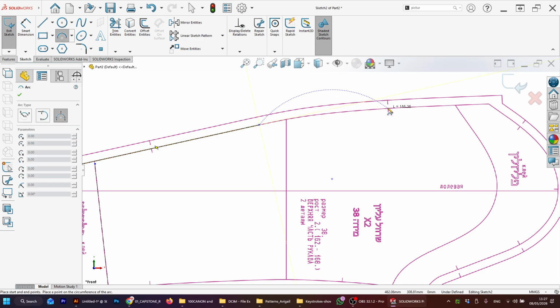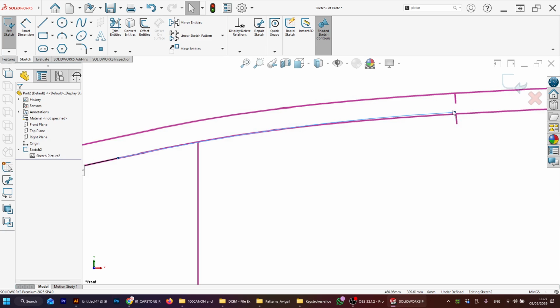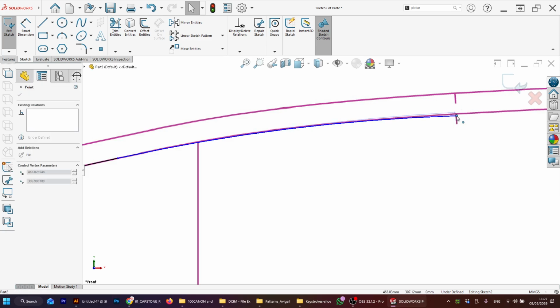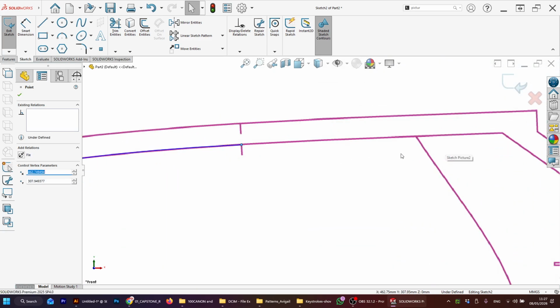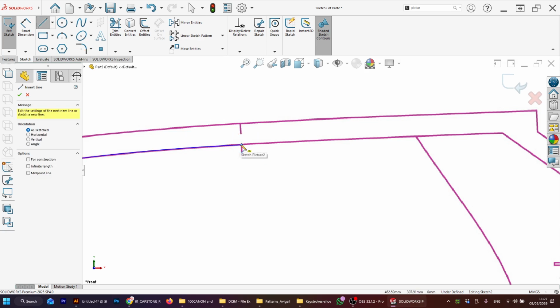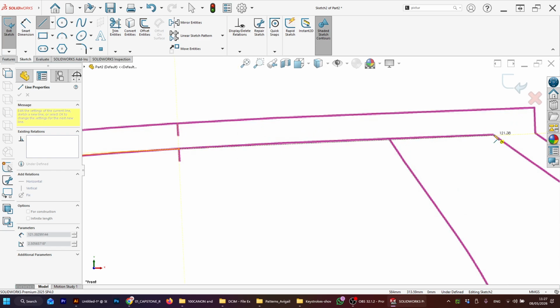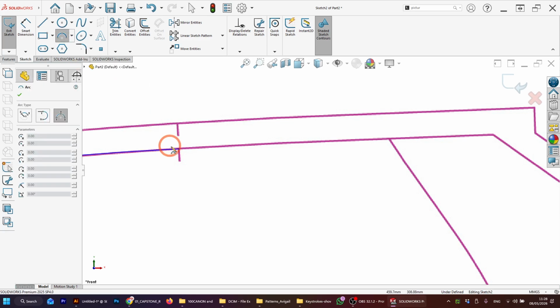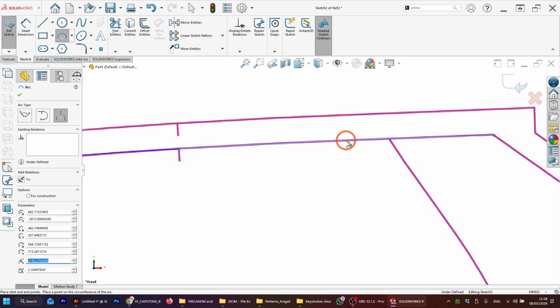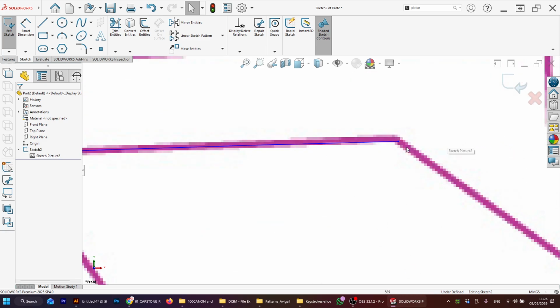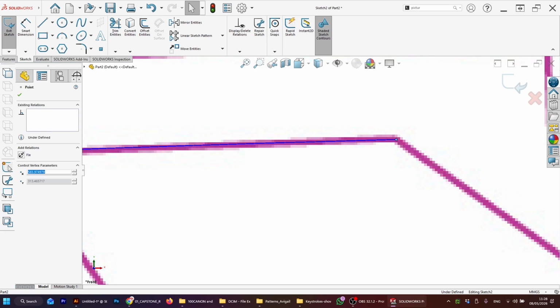One. You can try on the picking and go that. And then maybe that's when we're going to understand that these picking points are not just there for nothing. So see that it's marked, actually it's interesting that it could mark that it's the very end of this arc. And then I can go there, and here I can try to put a straight line, but the straight line is not exactly the way it was sketched. That's not exactly straight, it's slightly curved. So I use the 3-point arc. Here we go. So now we know that I can move that perfectly in the corner.